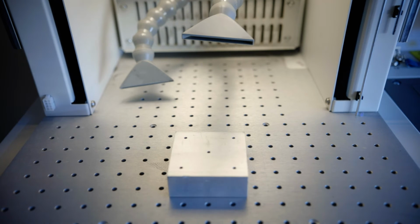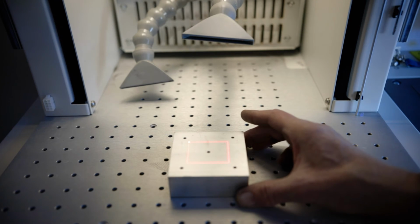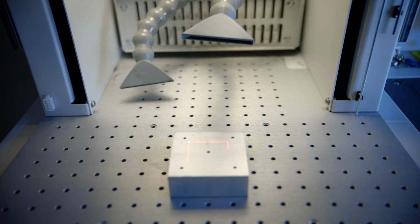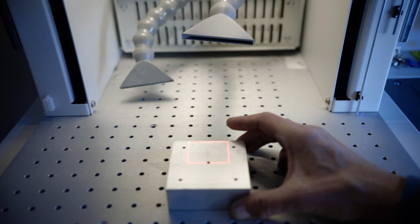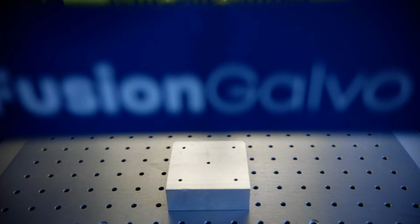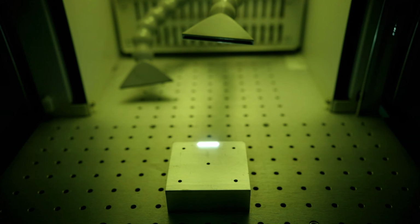At the machine, I'm going to do a trace function. And I can use that trace function to help me to align the part a little bit better. And we're ready to go. Actually going to move this down a little bit here. Put that right there. Turn the trace off. There's our job, and then we'll hit go. So the engraving is going to happen, and again, different increments, 10-degree increments, but 36 times.